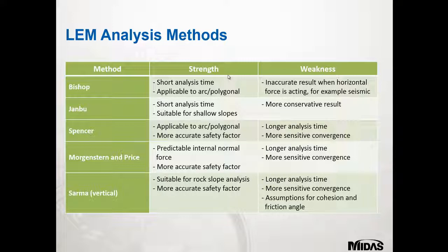So as mentioned before, different types of LEM methods exist, differing in how they solve the problem of equilibrium of slices by statics. You can see the pros and cons of each method in the table. Bishop's method is most widely used for slope stability analysis and is well suited for clays, as cohesive materials often go through rotational failure of mass volume about a point of rotation. For more complex problems involving highly heterogeneous ground with layers of different materials, and where the interslice shear force is expected to vary, one can use the Morgenstern-Price method using variable functions for modelling interslice shear forces.